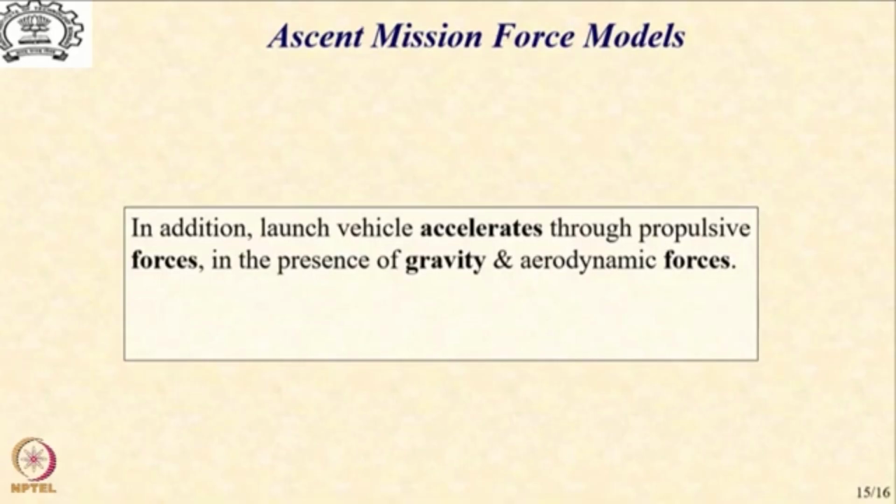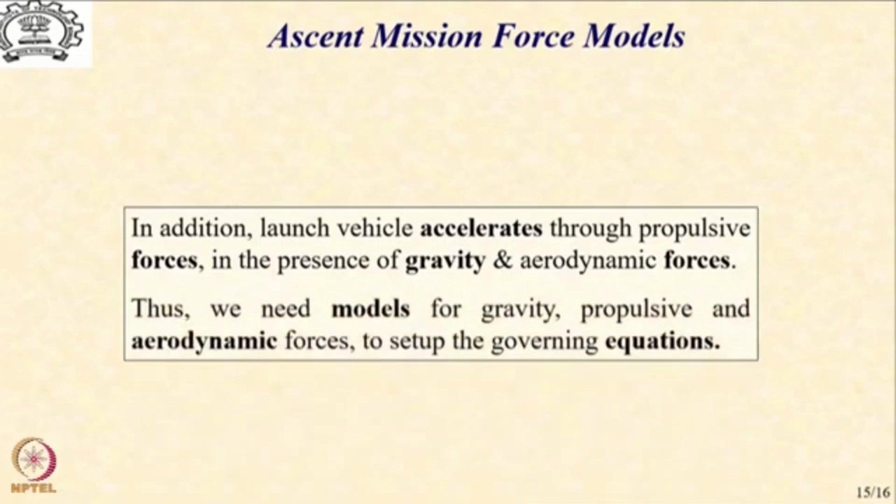Of course, we have also noted the fact that the launch vehicle is going to experience large accelerations because of the propulsive forces and will also be acted upon by the gravity and the aerodynamic forces. Thus, we need accurate mathematical models for gravity, propulsive and aerodynamic forces to set up the governing equations.